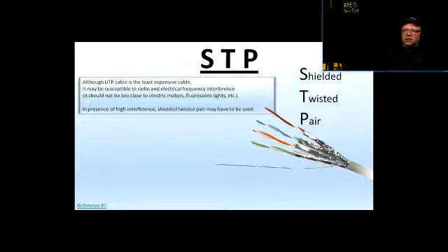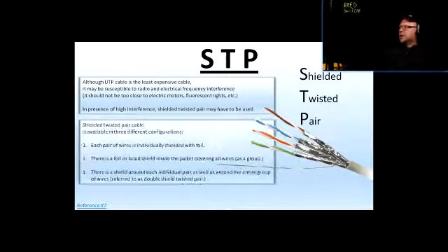There's a lot of signaling going on in there, and that's one of the biggest noisemakers. The other devices would be security alarm wires. They're also big noisemakers, so you would try to stay away from that, or anything that you can see as an electronic or electric device, maybe some relay switches or something like that. You want to stay away from that at least 1 foot in the construction environment here.